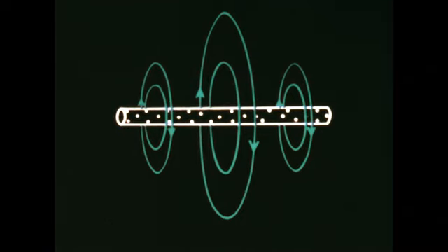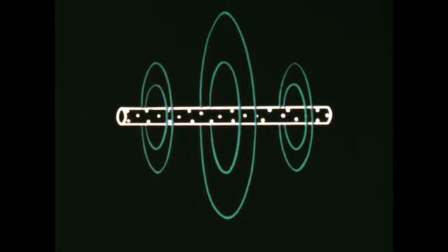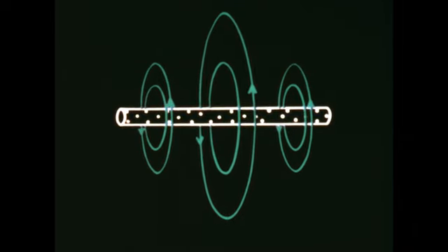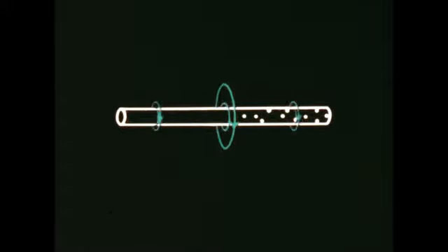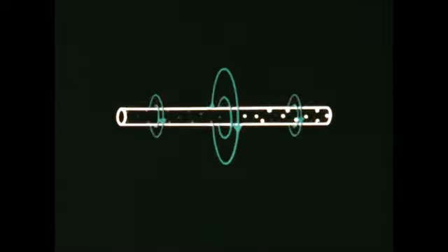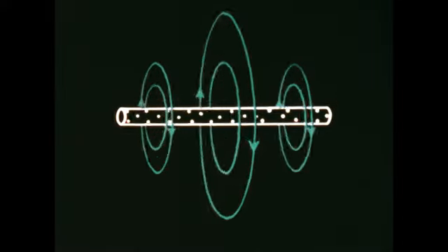When the flow stops, the lines of force collapse. As the flow reverses, the field again reaches a maximum. The lines of force are now in the opposite direction. The magnetic field thus reverses its direction at each half cycle of the signal frequency. This is known as the H field. The strength of this field is proportional to the amplitude of the current standing wave.